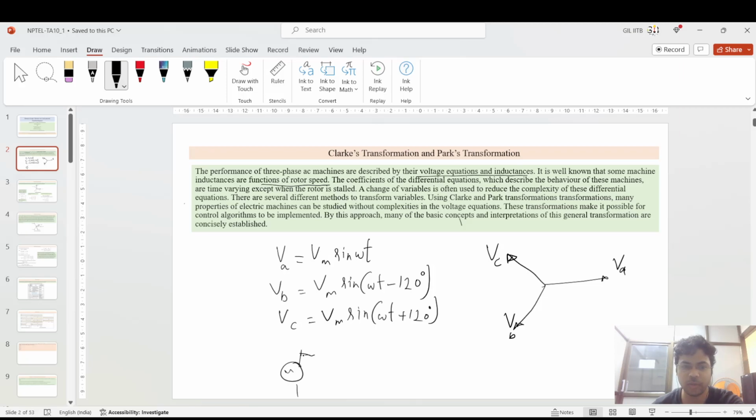Because if you see the synchronous generator itself, you have the EMF Eg at angle delta, the reactance, and then the terminal voltage, that is Vt. And this reactance term is actually the armature reactance and the self-inductance summation, that is Xar plus Xs. And this Xs is actually Ls minus M.